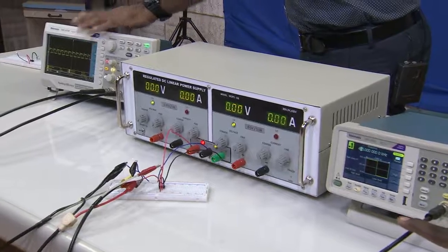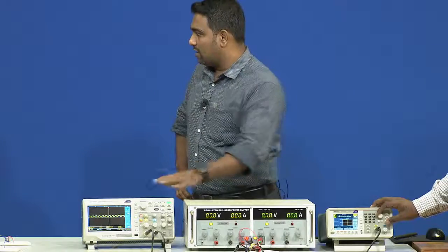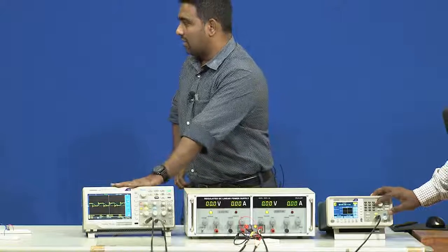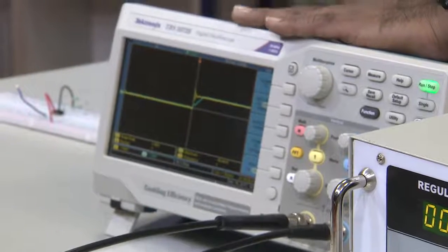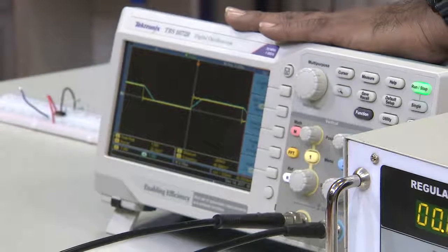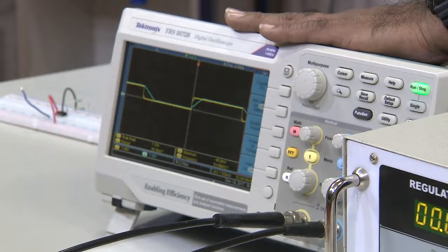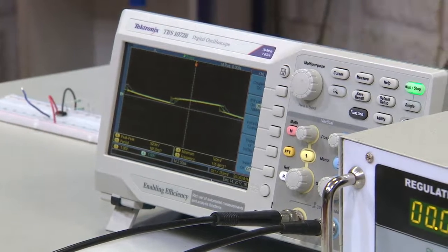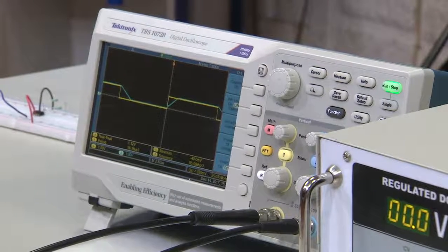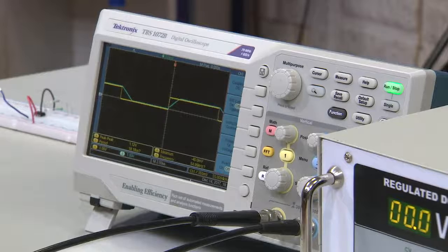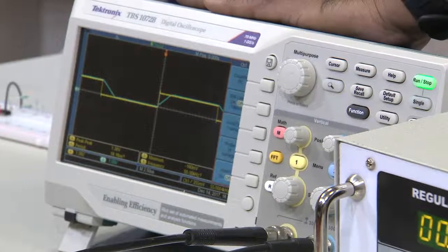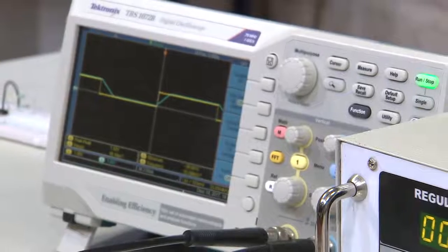But if he goes on decreasing the frequency, can you decrease it again? Yeah. If you see that he is decreasing the frequency, the distortion becomes less, and it is easy to understand or easy to measure the slew rate. So, this is how we can understand. From that we also understand that at a particular frequency the op-amp cannot be operated, that is the maximum frequency at which the operational amplifier can be operated. So, there is an easier way to understand at what frequency the operational amplifier can be operated. At that frequency, the slew rate will be distorted.